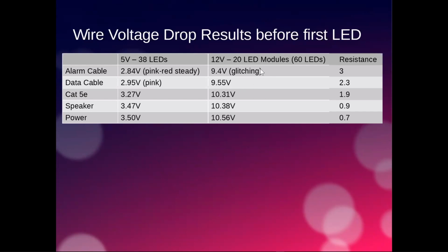But what you will get is signal glitching problems where the pixels glitch. And depending on the sorts of data you're sending, it'll either flash on and off, or it'll glitch different colors, or in some cases it will lock on to white and just stay white all the time. And I've definitely seen that in my display, and never fully understood what was going on, but I do now. But you're much more likely to get this with 12-volt pixels than you are with 5-volt pixels.